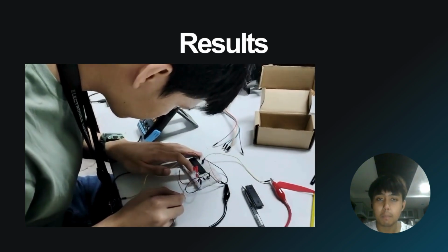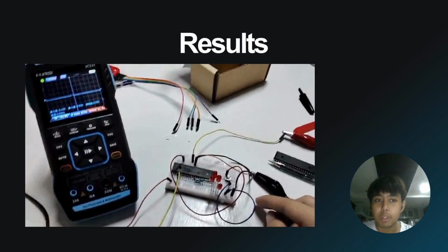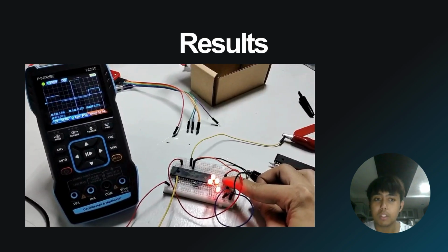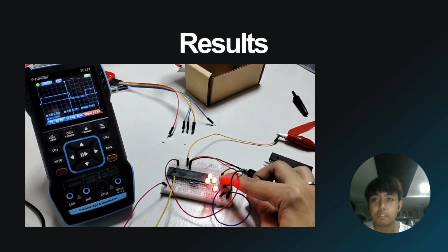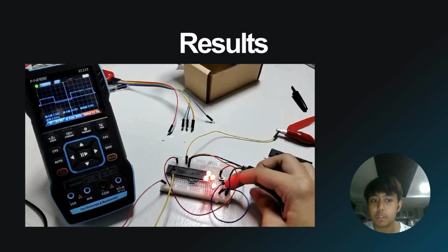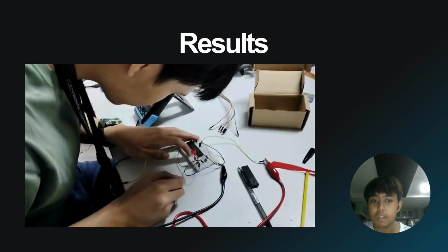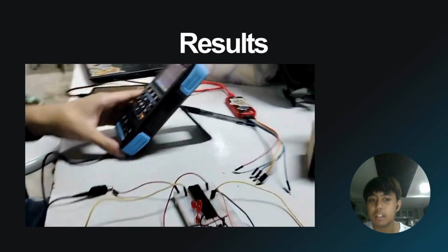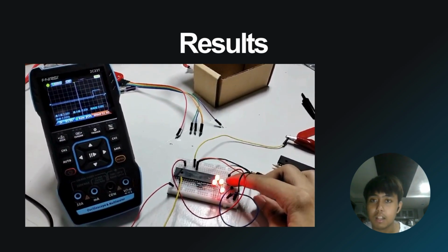In our successful attempt, Myrnie had troubleshooted the circuit correctly. Four LEDs were connected to pins 3, 4, 5, and 6 respectively, and each had a 220 ohm resistor that is connected in a configuration just like the first part. The program was created to use interrupt on change to toggle the LED whenever the state of the switch was changed. The switch caused an IOC interrupt, but this time every LED toggled, which was an enhancement of the first part of this lab experiment.